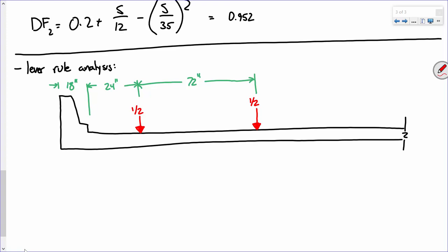Now, from the edge of the deck to the exterior girder is how far? Somebody else had given me that number earlier, the 3'6", so that's 42 inches in to where that exterior girder is. Just by sheer coincidence, that's right under that load, because the dimension from here to here is 42 inches, and that just happens to be 18 plus 24. That really truly is a coincidence. Ultimately, what we're after is this reaction.